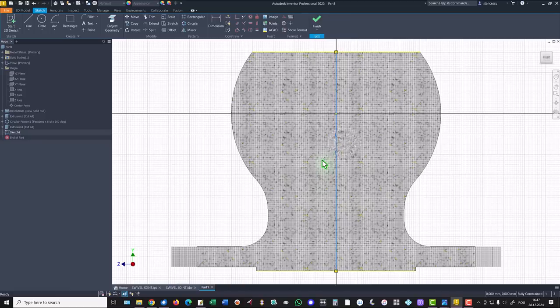This is a center line. Okay. Then again arc, starting with the center, starting with this, but now I write here the radius of 80 and I draw an arc to here. You see, one dimension needed. Only this end is not placed finally.